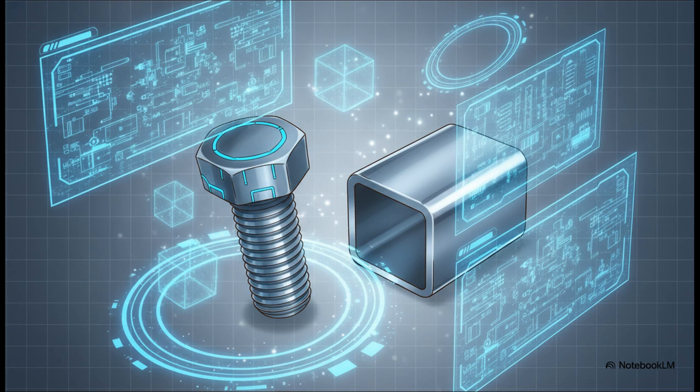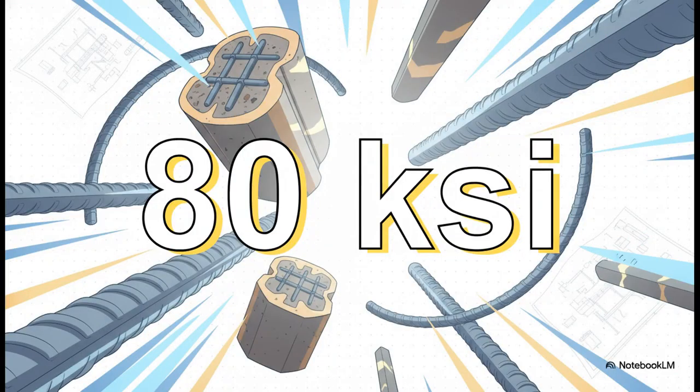They also expanded structural integrity provisions for connections and added limit states for constrained access torsional buckling. These aren't just minor little edits, folks. These upgrades are the literal reasons we are safe sitting inside modern buildings today. And to highlight exactly how far we're pushing things, just look at this specific number, 80 KSI. The 2016 specification actually increased the limit on reinforcing bar strength to 80 kips per square inch for composite columns. This perfectly shows how engineers and metallurgists are constantly pushing material limits further and further, which is what allows us to build taller, lighter, and stronger structures than ever before.